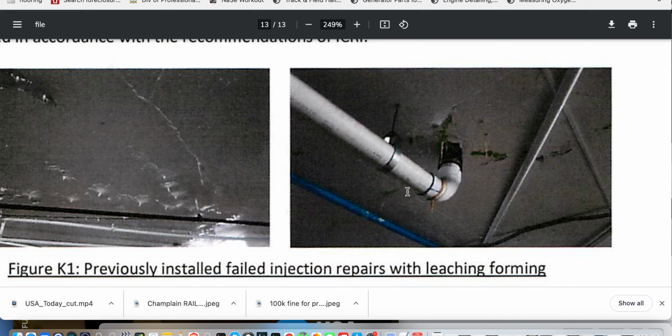And don't forget, over there by the cars, by L, they've got that plastic panel up there to stop water from coming through. They've got those panels in quite a few places. I counted 4 places that those panels are in. So you can't tell me this garage wasn't suffering deflection.